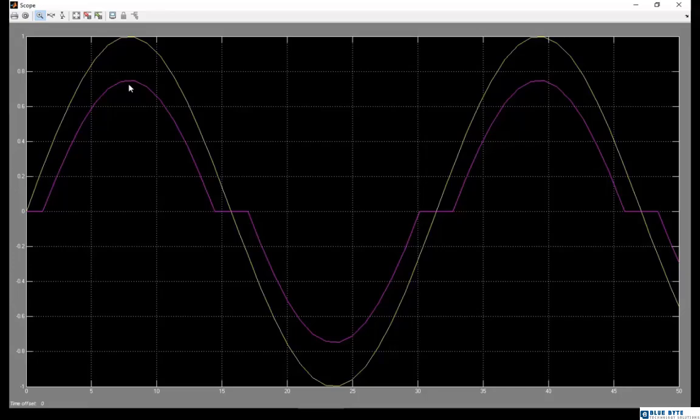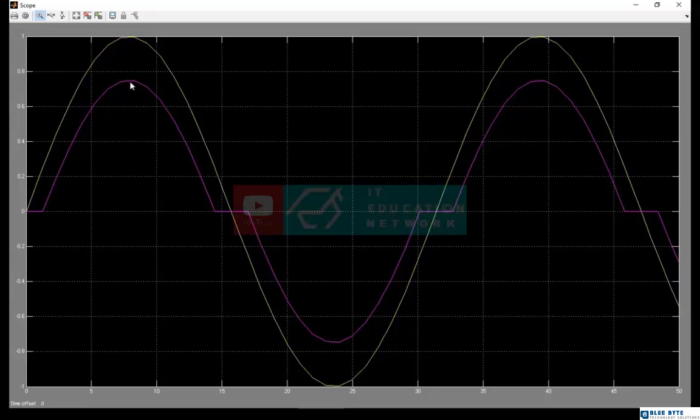It means that our output signal isn't this signal, it is the main signal minus 0.25. And then when it reaches 0.25 again, our signal gets 0, and after that our main signal will be reduced by 0.25. This process continues up to the end of simulation. This is a useful block in simulation because you can set your input in a specific zone.